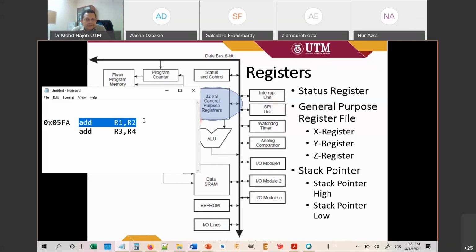All right. So what happens when you download your program from your Arduino IDE into your board? Your Arduino IDE does not actually send all these words into your Arduino Uno. When you click upload, the Arduino IDE will compile this into machine language.